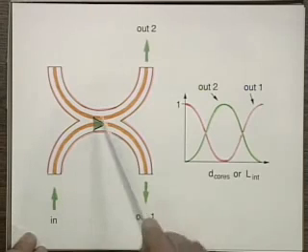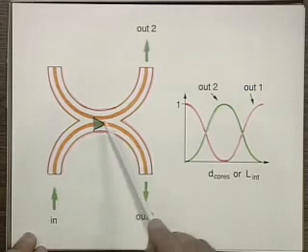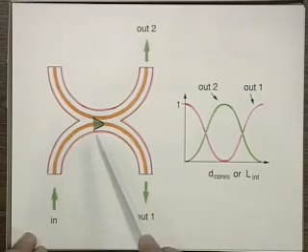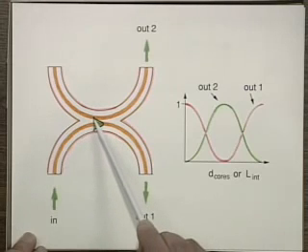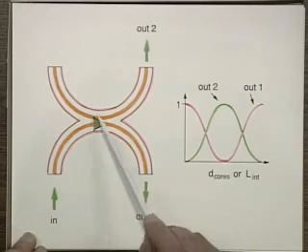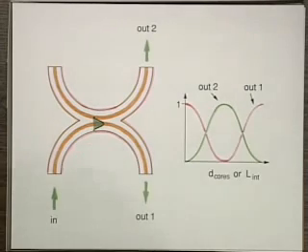And this is great because it's pretty low loss and is used, of course, all the time today. These couplers can be what we call the polished type or the fused type and so on. There are different types of couplers, but basically they work on that principle of bringing the two cores close enough together so that the evanescent wave, that little tail of the field distribution, will propagate in the other core and will drive the dipoles over there. All right, so that's basically the principle of a coupler.